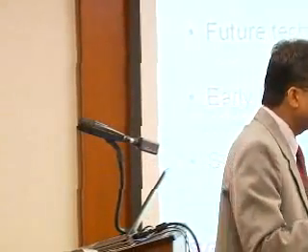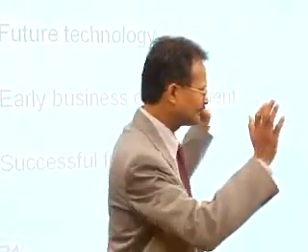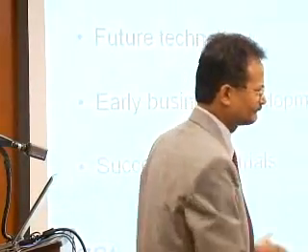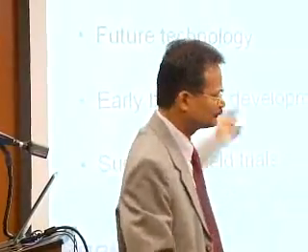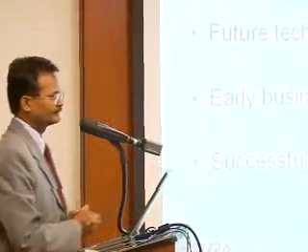Yes, what I want to do is probably to have 2 identical bit error rate testers from eBay working at 166 megahertz, where I have electrical inputs. Once I have them, I will connect them to my detector, and I'm ready to go. I have all-optical bit error rate testers, but I need electrical bit error rate testers to test it at 166 megabits, get the eye diagrams, and then it has either been proved or disproved in the real-world scenario. We have transferred videos and files using our techniques, but you need to have the exact bit error rate tester.